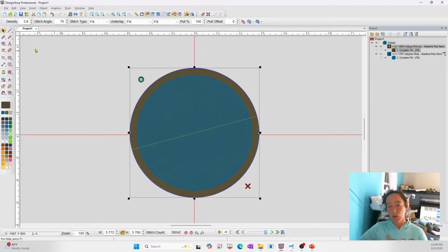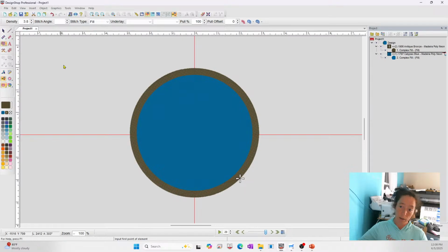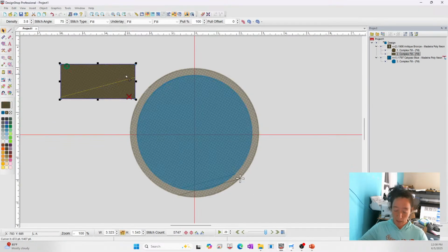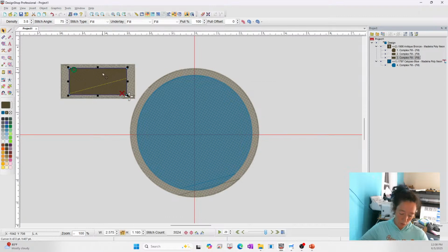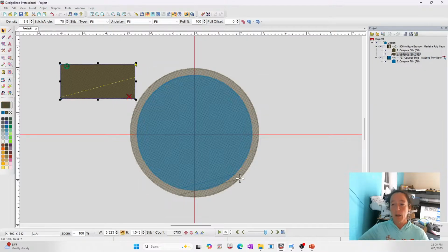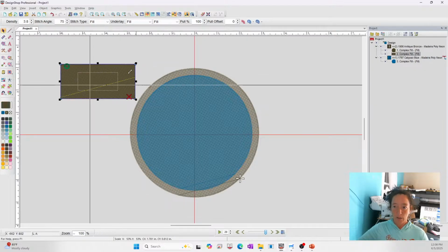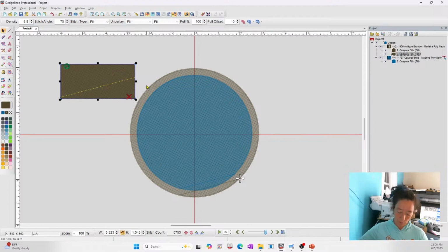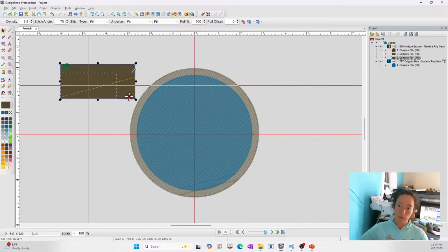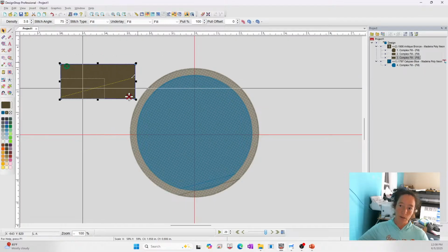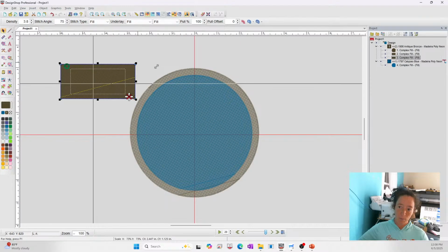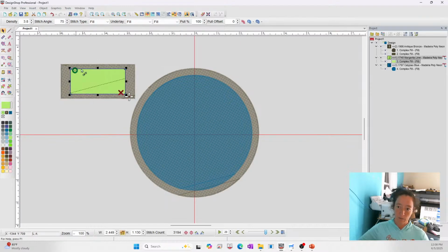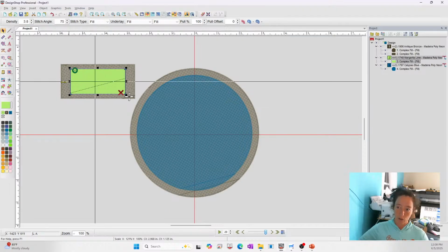If you draw something that's non-concentric, like a rectangle, and I copy and paste that, and now I drag it, holding Control, undo, delete that. So what I did is I held Shift Alt, and that's the same thing I did on that circle. Shift scale keeps everything uniform. Alt makes it go from the center. So I can scale it down, but you'll notice I get an uneven thing here and here. So I then would have to do an Alt and just drag this around.